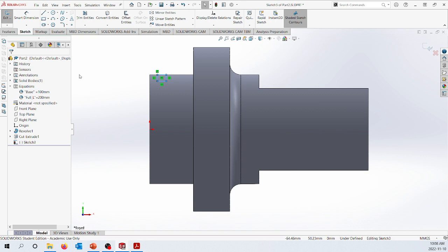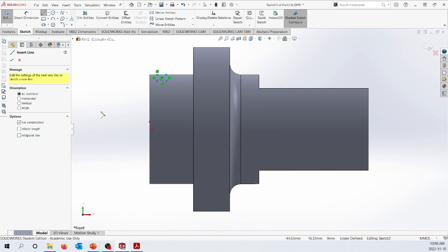I need an axis around which it can revolve. So I'm going to put down a center line. I have a nice easy thing to snap to here because I made my whole part on the origin. My part is centered on the origin. But if I didn't have that, I could still use other features of my part, because this edge over here, I could snap to its center. If I didn't have that, I could sketch things out, tracing my parts to create a center.